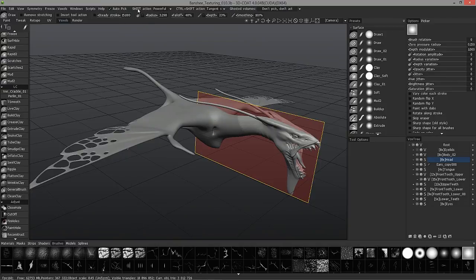For example, when you hold the shift key in other sculpting applications, it will smooth on the fly, and you could always do that in 3D Coat, but now when you're in surface mode, you have a host of options when you hold the shift key to perform different types of smoothing. So you have a standard smooth, powerful smoothing. What this does is it tries to apply optimized geometry as well as smoothing. Relax typically will just try to average the vertices. Tangent smoothing will try to maintain the shape, yet give you a more optimized geometry.